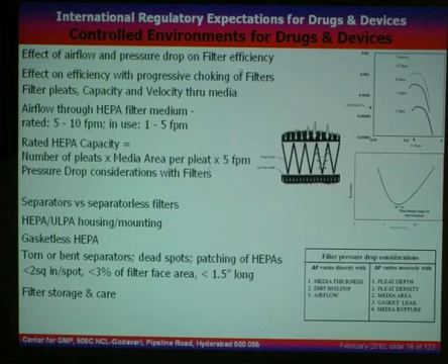It never occurs to you to specify the number of pleats and the total media surface area, and what you're paying for is for that media. So make sure that you get your money's worth. Now, what else can we learn about the HEPA filter? Now, let us see pressure drop across a filter is influenced by what? Now, the pressure drop